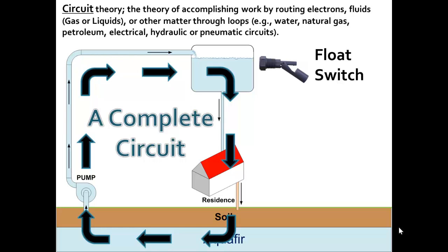As the water lowers in the tank, the float starts to angle down, and when it gets far enough down, gravity carries the weight inside of the switch bulb to close the switch. Then of course it turns on the pump, the water pumps back up, and the float starts floating back up until it's above level and tips the other direction, the weight slips the other way, and opens the switch.